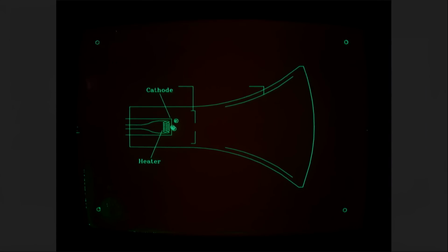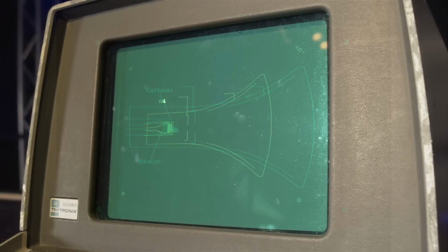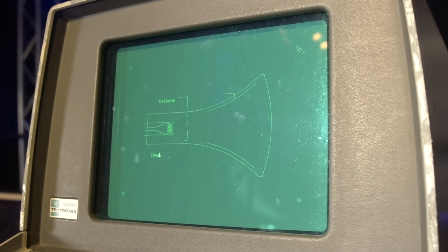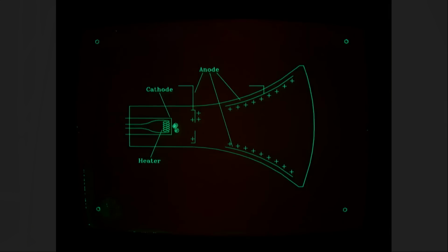Cathode ray tubes came a long way in the decades that followed. To build up the kind of CRT you'd use for a display, you'd have elements like the following. First, the electron source at the back of the tube, called the gun, would have a heated cathode. More heat makes those electrons more eager to leap forth once voltage is applied. Of course, to have voltage in this case requires a negatively charged cathode to shoot the electrons and a positively charged anode to receive their charge and provide a path for current to flow out of the tube.